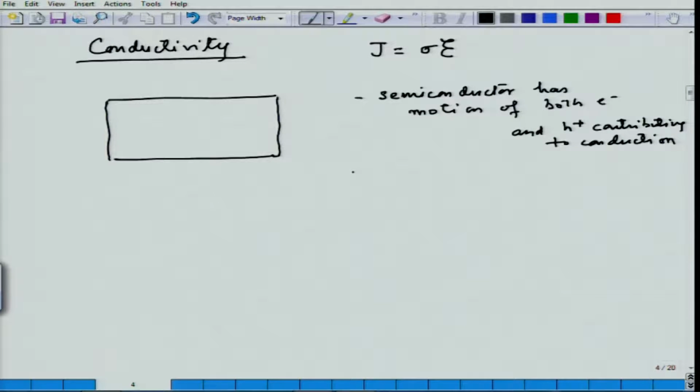And I am going to treat these electrons and holes as classical particles like we did earlier. The only difference being the electron mass in the conduction band is going to be the effective mass of electrons in the conduction band, and the hole mass is going to be the effective mass of holes in the valence band. So, this is what I have taken from my quantum mechanical picture. I have changed the effective mass, otherwise I am going to assume the similar picture that we had earlier.